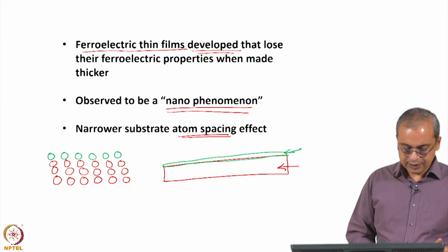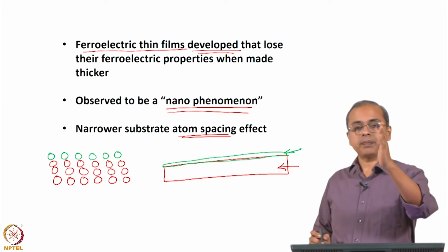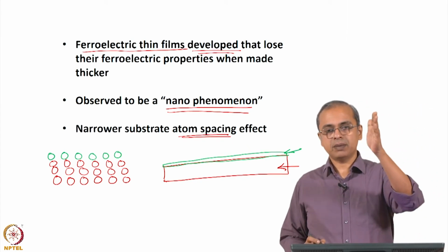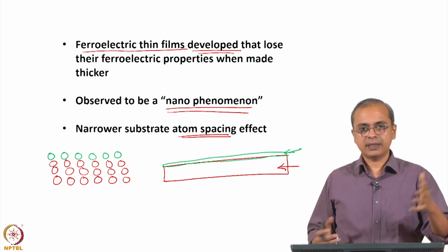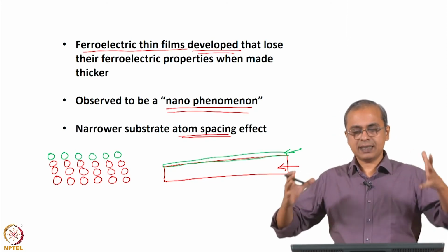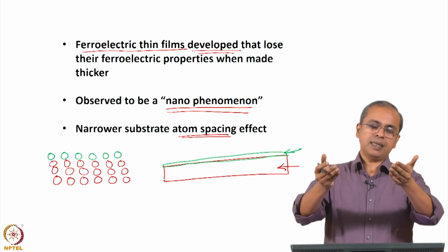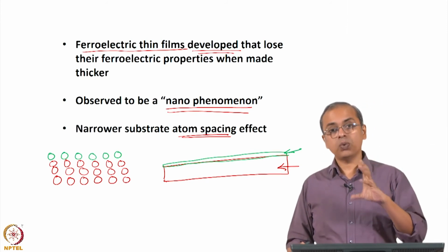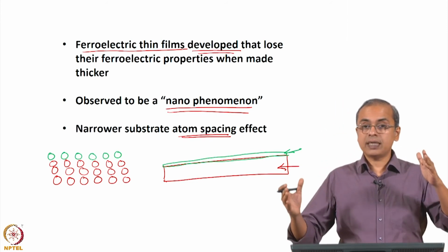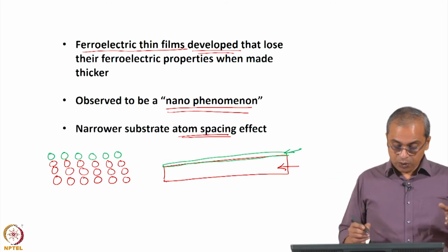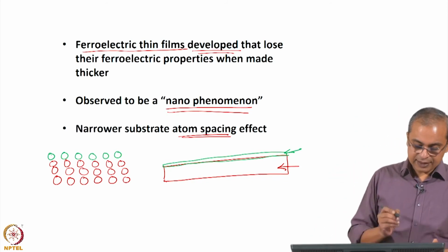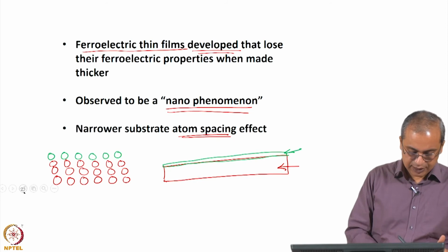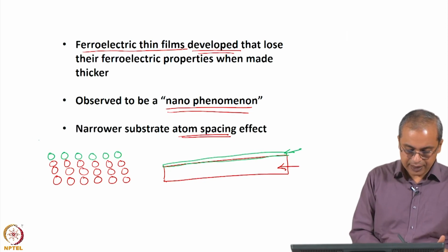Generally what happens is the atoms tend to line up, because that is when they have the least amount of energy relative to other locations that they may have. The crystalline structure tries to sustain the same crystalline structure on either side, that is when the overall system has less energy. So, they try to line up. Now if your original material actually had larger spacing, let me just exaggerate it here, let us say as a separate material it had spacing like that.